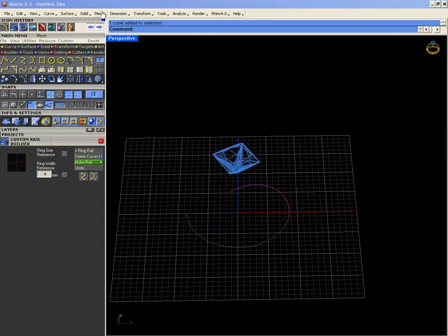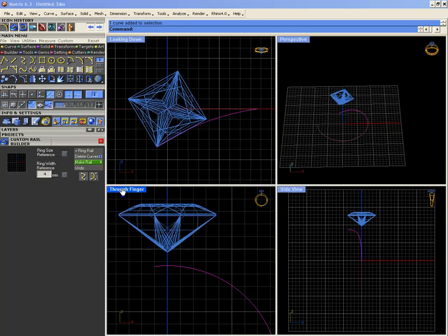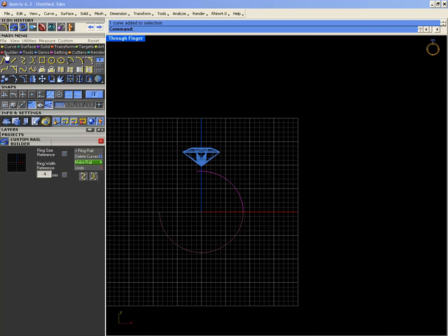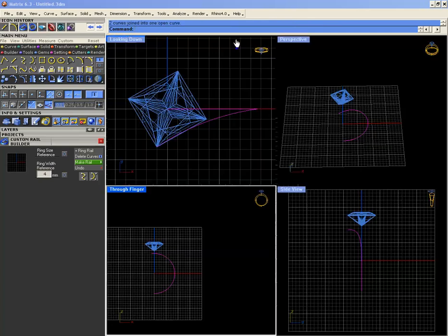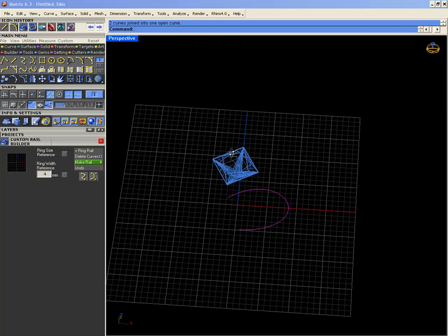You can make it half. Let's say I trim this curve, a line, F4, straight down, and then I trim it with trim option, so I have it half. I select both, I join them, and then I rebuild.